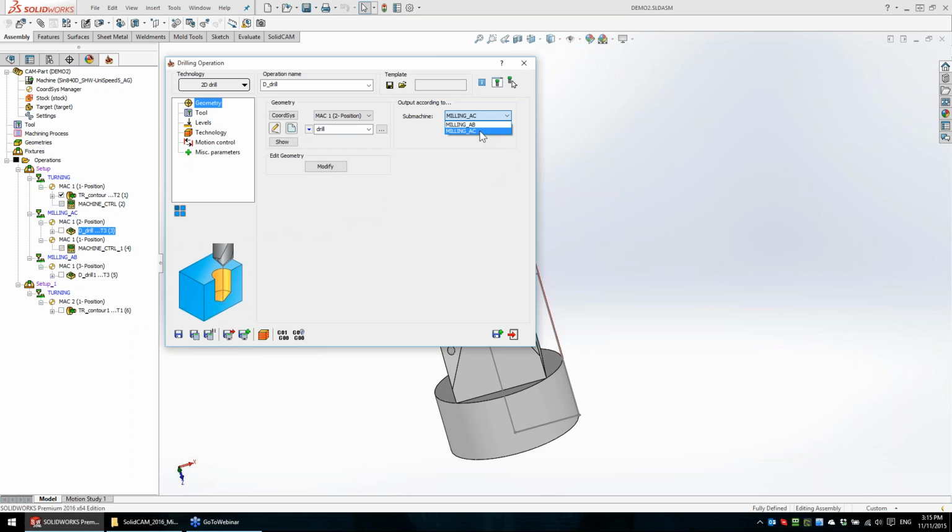A and C, that's a head-head kinematic, or A and B, one axis on spindle, one axis on table, that's a head-table kinematic. Both options work, and we just need to select them, depending on part position on the table, the angle of a tool, and the machine limits, range.